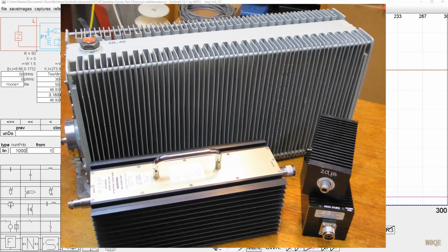They are not symmetrical. Even though the resistors inside of these things are symmetrical in terms of values, the one resistor on the input side, particularly for attenuations greater than a couple dB, sees the bulk of the power. And consequently, that resistor is a large resistor. In the case of this attenuator right here, the resistor on the input occupies most of the space in here, and then the other resistors, there's a piece of transmission line that goes around it. This one's all done on a flat surface inside, but the other resistors are considerably smaller. That means that if you accidentally apply the power in the wrong direction, you will immediately blow up the resistor